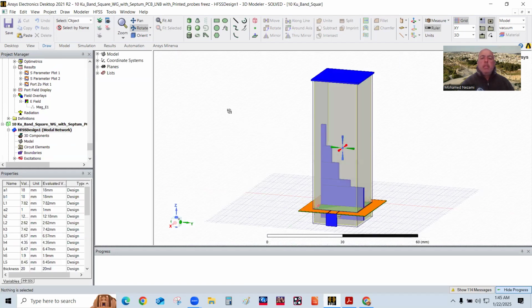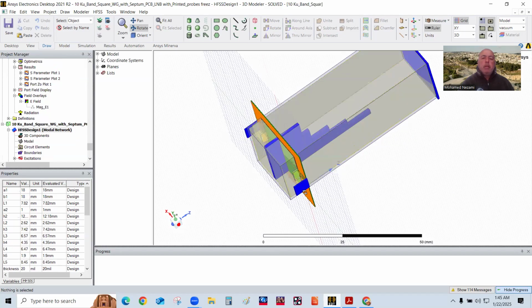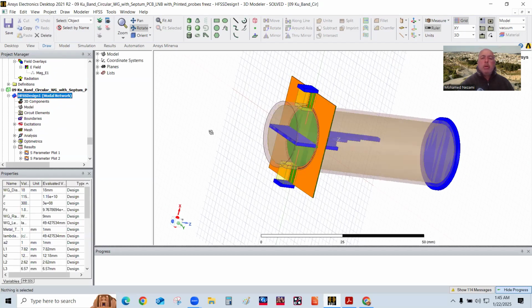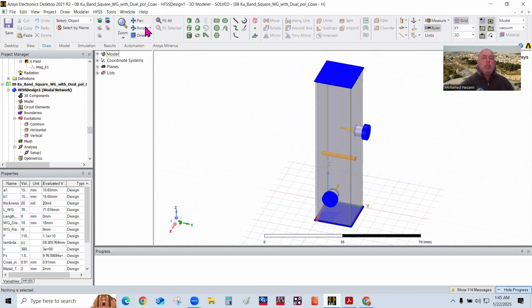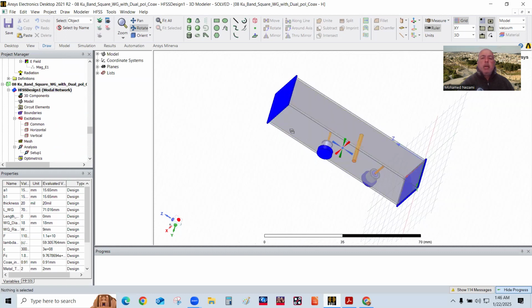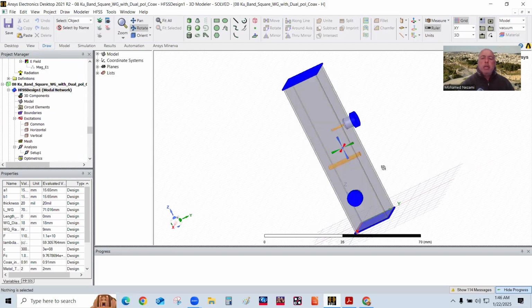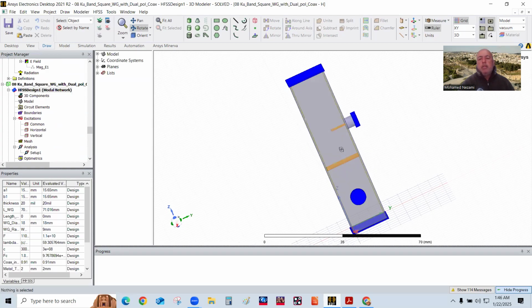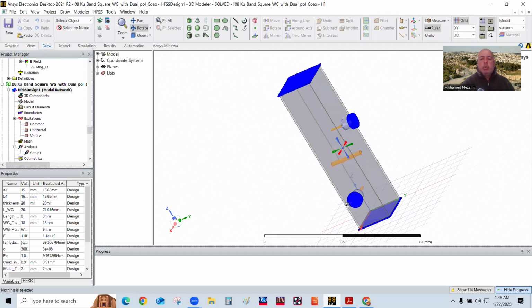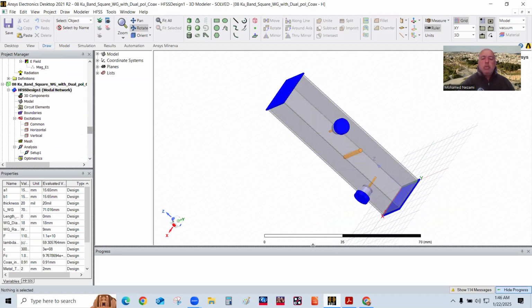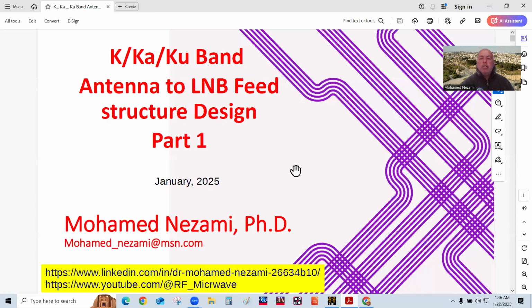So we have either a dual feed, vertical and horizontal, with septum, or we have something similar to this one here, where you have a sort of cheap septum, which is just a grid line that will act as a reflective quarter wavelength back short to one of the polarizations, where it looks transparent to the other. So as you can see, this series is busy.